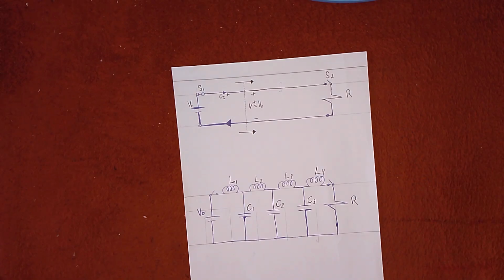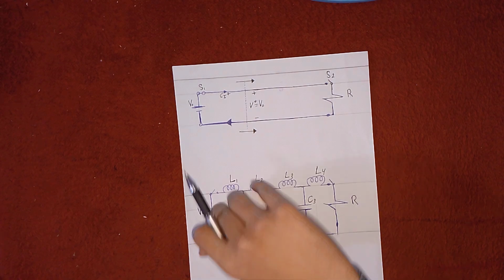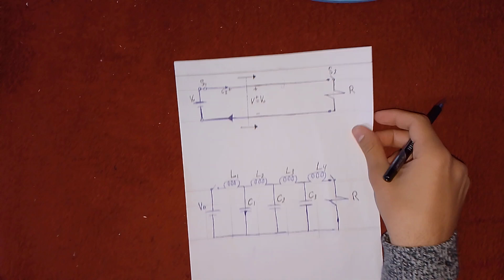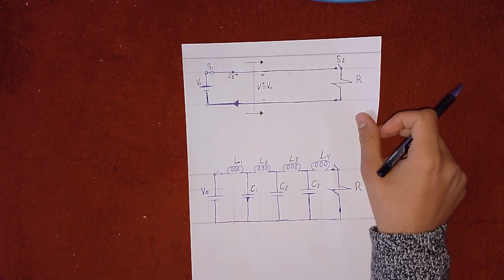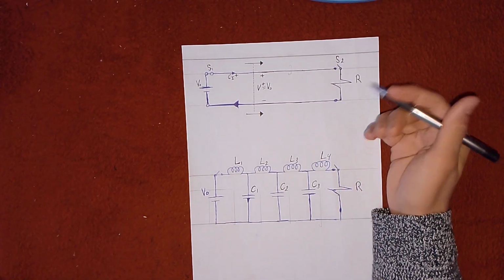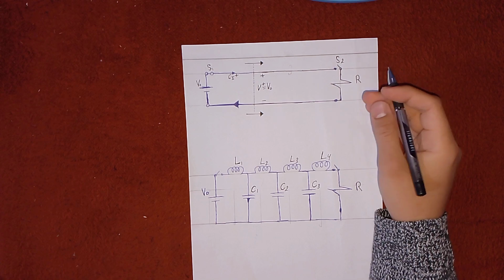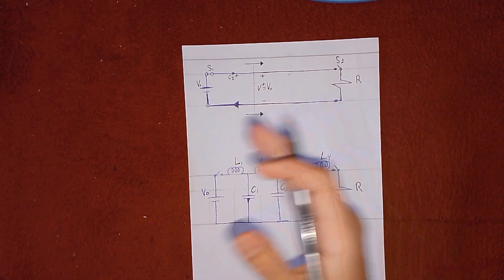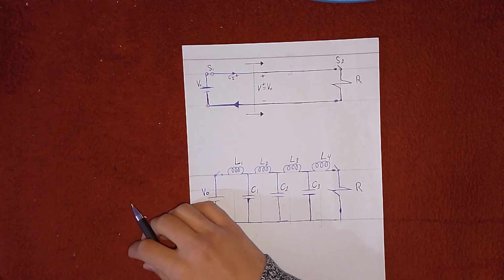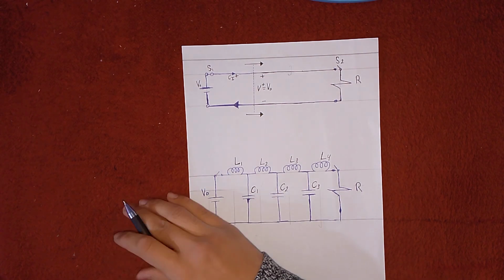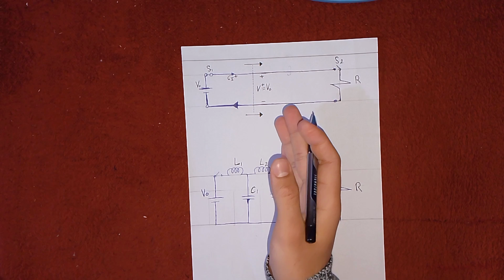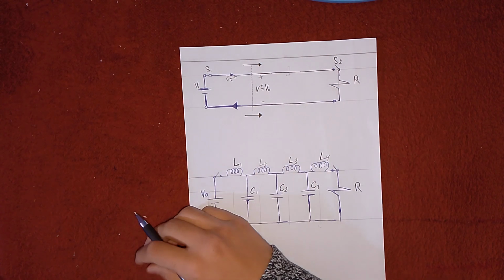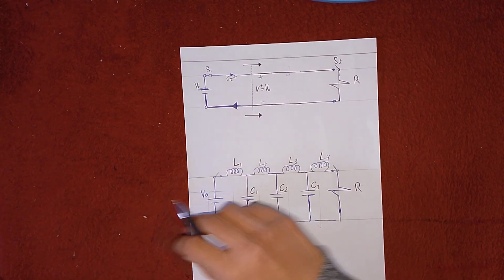Hello everyone. In this video, we'll explain the basics of transmission lines in a simple and clear way. In basic circuit analysis methods, connections between elements are assumed to have negligible length. This enabled us, for example, to take for granted that the voltage across a resistor on one side of a circuit was exactly in phase with the source on the other side. But when distances are sufficiently large between source and receiver, time delay effects become appreciable, leading to delay-induced phase differences.